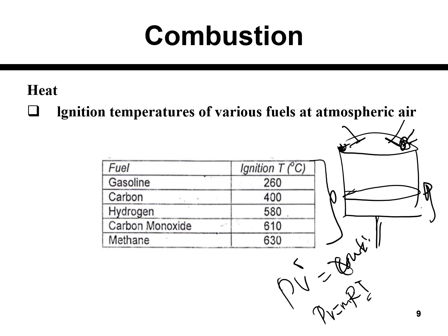A small combustion will spark, and then generate other combustions that expand into the other areas. This will create what we call a shock wave, because combustion also creates another pressure rise in the cylinder. So it will create a shock wave inside the combustion chamber and cause a sudden pressure increase.